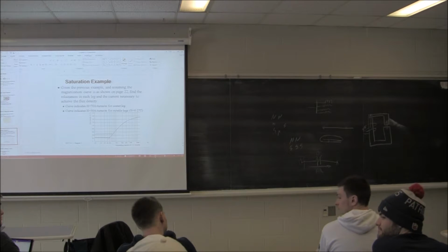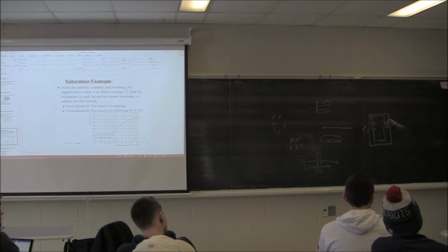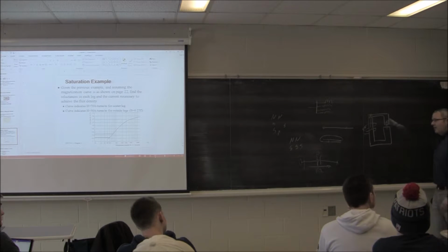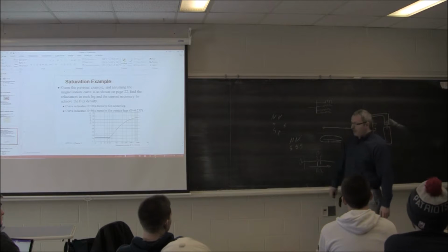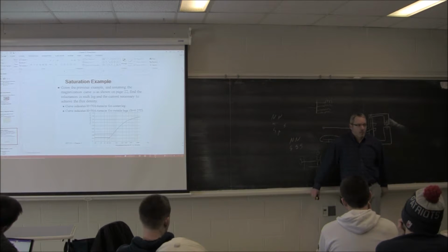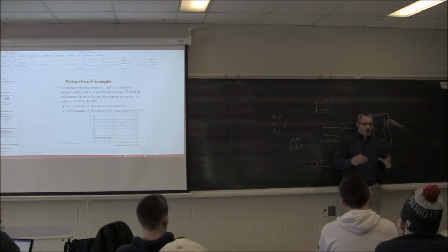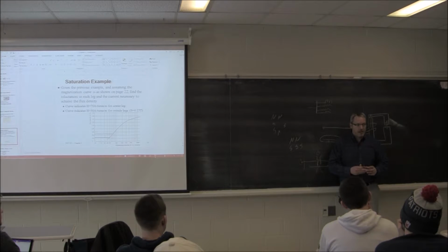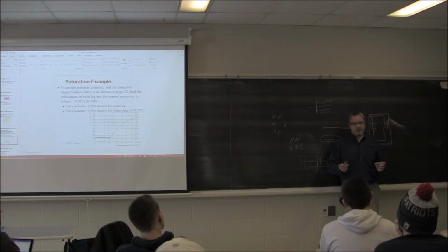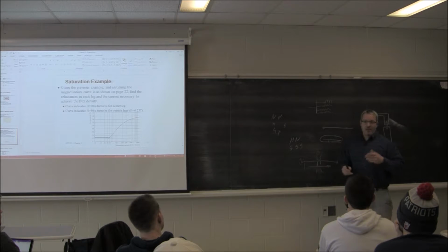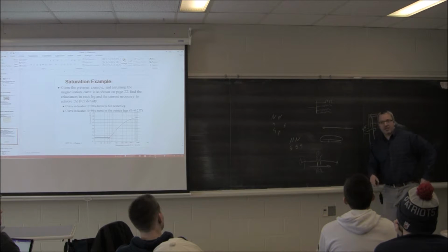Are there any gas insulated systems on campus? No. Gas insulated, if anybody's wondering: if you get high voltage stuff and you don't have a lot of space in the room, you can't use air, so you use SF6, sulfur hexafluoride, which is a really good insulator. Typically you'll see GIS, the nickname for it, in really tight spaces. Like if you're in New York City and you don't have a lot of real estate, you can't run 345 live, so they run it in GIS, and that provides the insulator, so you can run them within a couple feet of each other, and it's safe to do that.